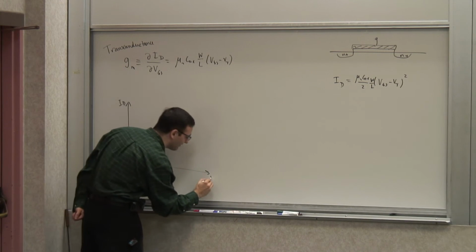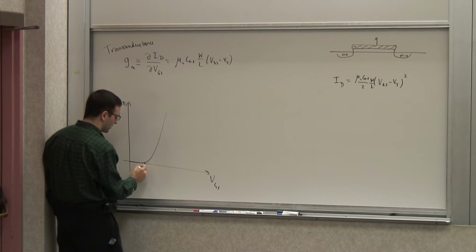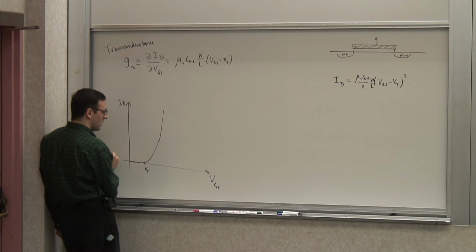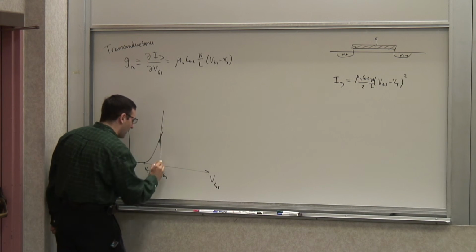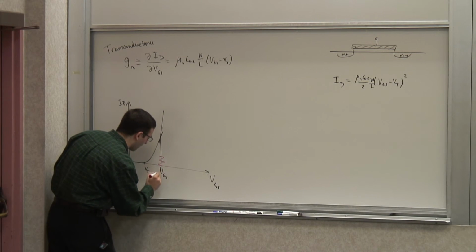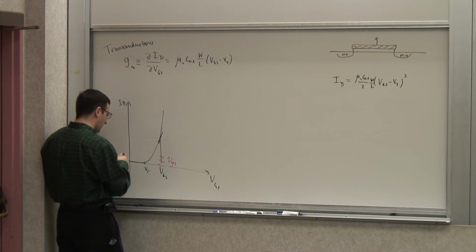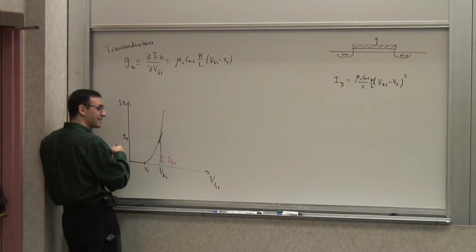So if you look at I_D versus V_GS curves, based on the simplified model, the transistor is off up to V_T. We know there's some threshold current here, really. And then you go up quadratically. Now, at a given capital V_GS, if I apply a small signal fluctuation, v_gs, what kind of fluctuations can I expect around my quiescent capital I_D?